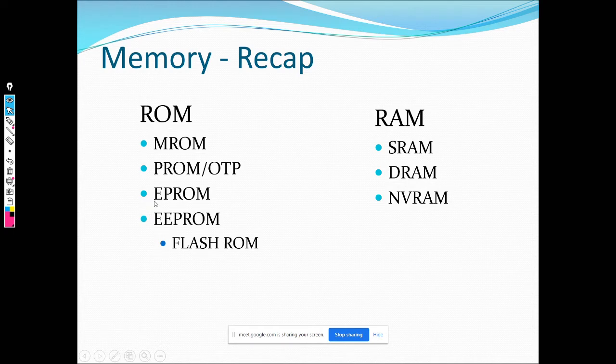There's another thing called EPROM, erasable PROMs, where you can erase the data and program it again, but this is not very flexible. The BIOS chips that we see are all EPROMs. There will be some BIOS setting that you may want to change. These days computers support different technology, but earlier, and even now in testing, they have EPROMs for BIOS. Every time you want to change a BIOS configuration or reprogram the BIOS, you take the ROM chip out, put it on a specific device, and burn it, meaning you program it.